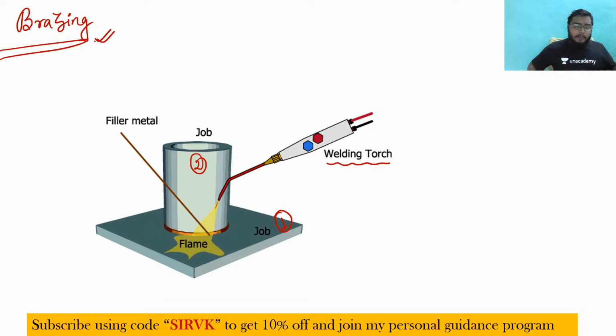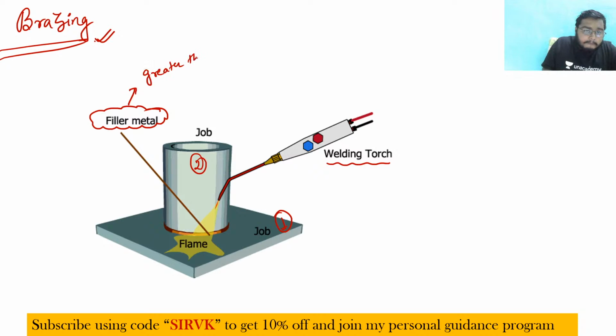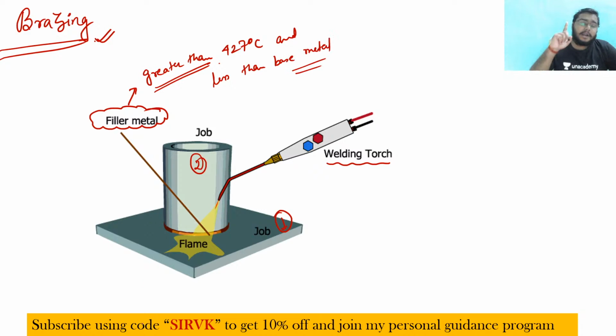The process is the same. What is the difference here? The difference is the filler material. The filler material that we are using to weld has a melting temperature greater than 427 degrees Celsius and less than the base metal. So this is the first property of the filler metal in brazing.